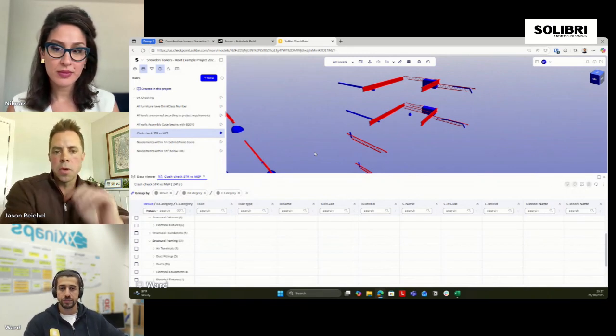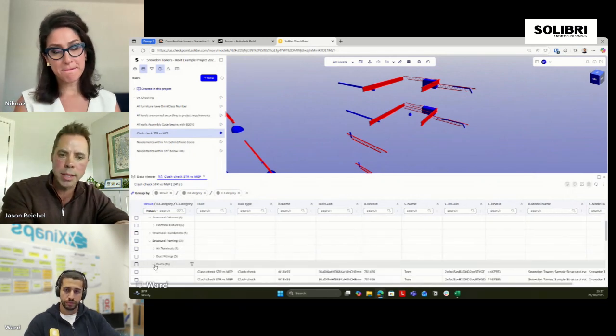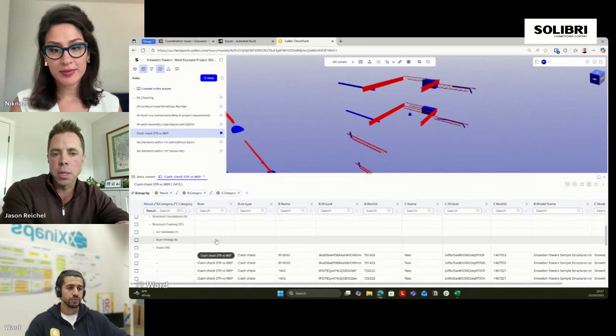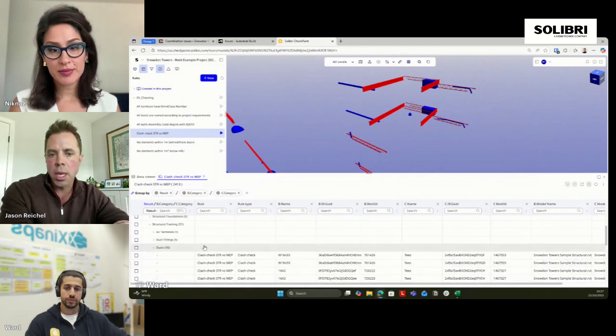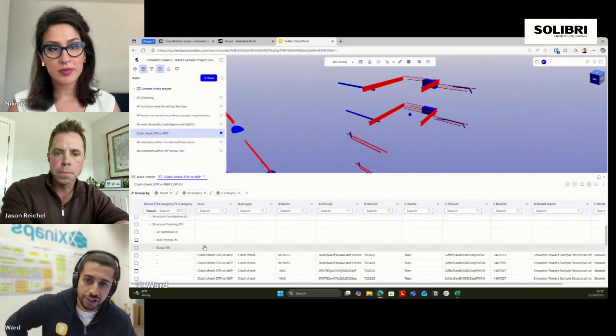Yeah, so I think what you did there in the data viewer is exactly what I was getting at. It was just some simple drag and drop. You're organizing your results and kind of creating a clash matrix of sorts where you can quickly hone in on the different areas that need to be looked at. Exactly. It is similar to the clash matrix.